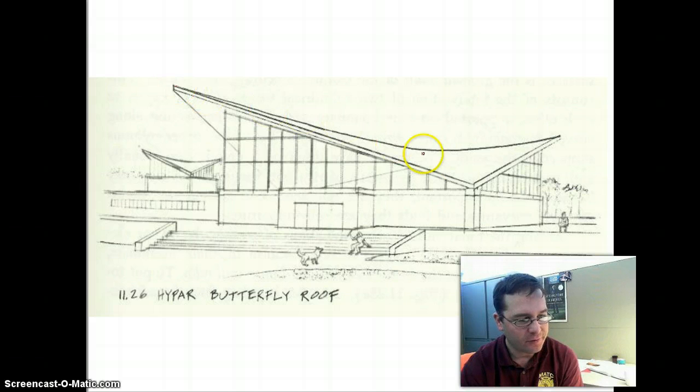This type of structure is typically made out of reinforced concrete, and its load is borne on these points out here on these columns. Now, that means that there is this kind of curved shape that this thing takes on between the columns, and just like any other arch, this curve wants to flatten out and produce an outward thrust on these columns that are supporting. So these columns have to be robust to that type of load.